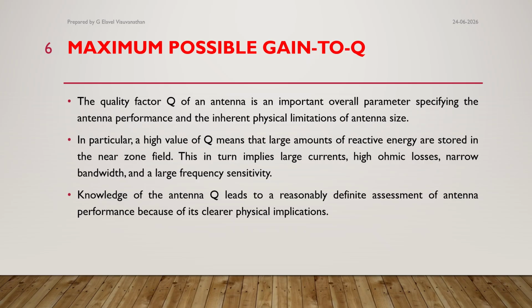Once we have a high quality factor Q, it means we have a large amount of reactive energy stored. This implies large current, high ohmic losses, narrow bandwidth, and large frequency sensitivity.